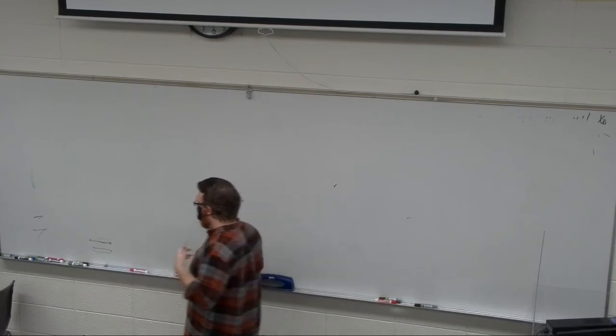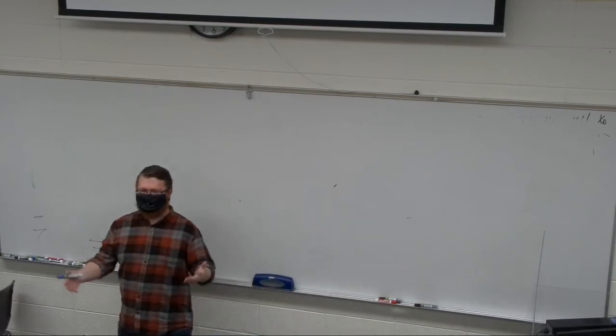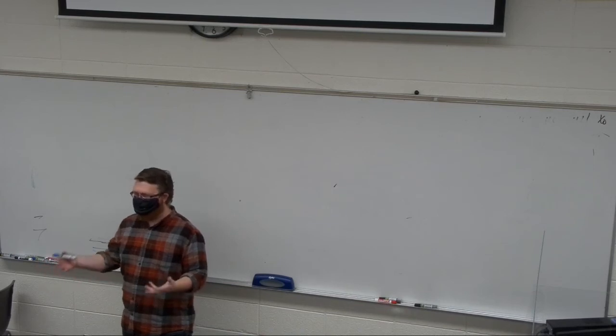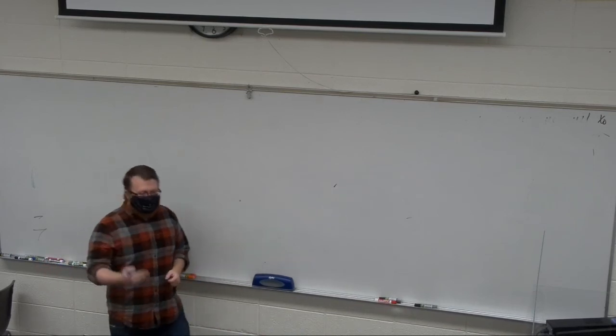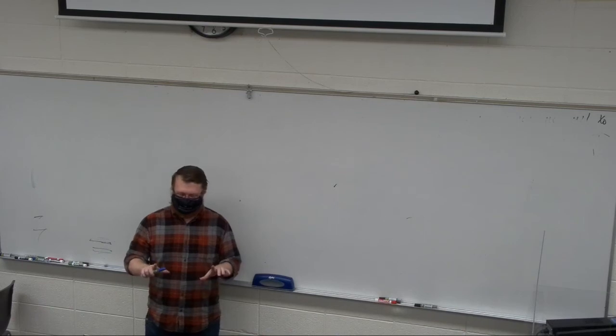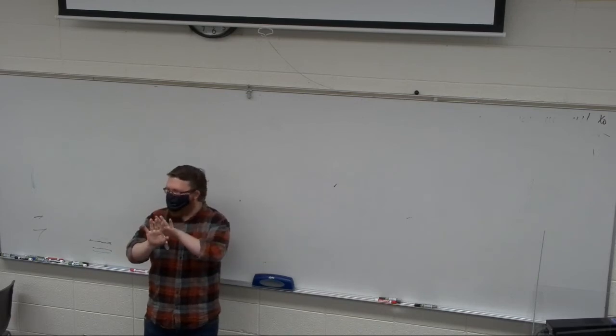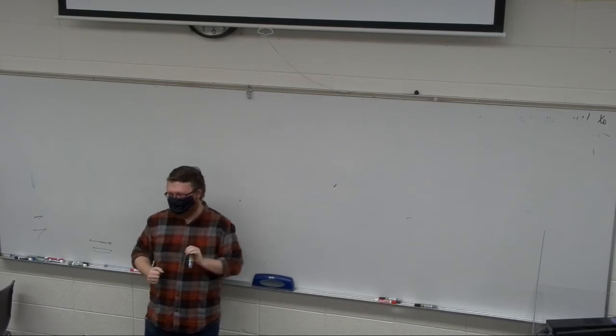Part of this lab is going to be drawing the block diagram of your modules and labeling the ports to the modules and that kind of thing. Be careful when you have these controllers, right? You have the SPI interface and then you have the SPI controller. The SPI controller will be your module, right? So it's going to have its inputs and outputs, and you're going to tell it when to tell the DAC to write.